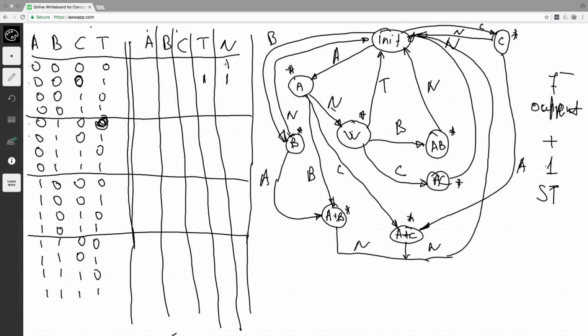The more ones we have in any one of these columns, the easier it will be to optimize those functions. So having one in column N in this case doesn't change anything from the perspective of the logic, because having 1 or 0 in this position makes no difference, because timer expired in the state when none of the inputs is present will result in changing to this state.